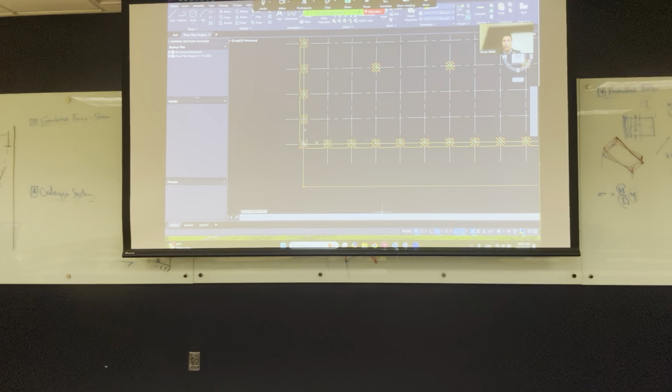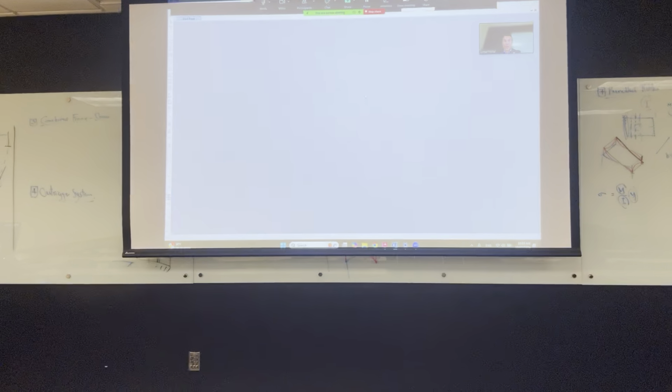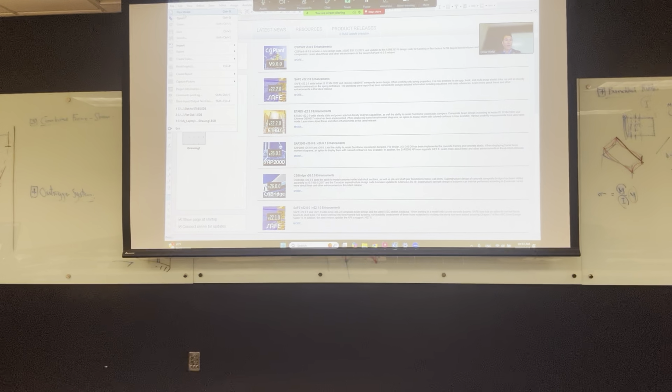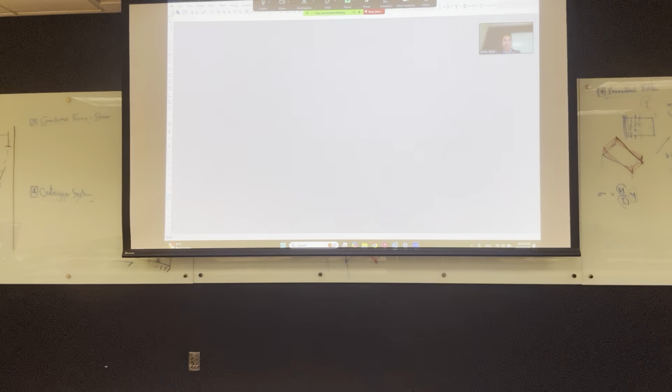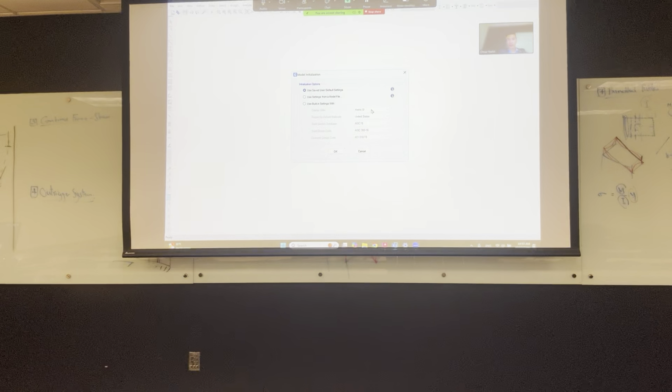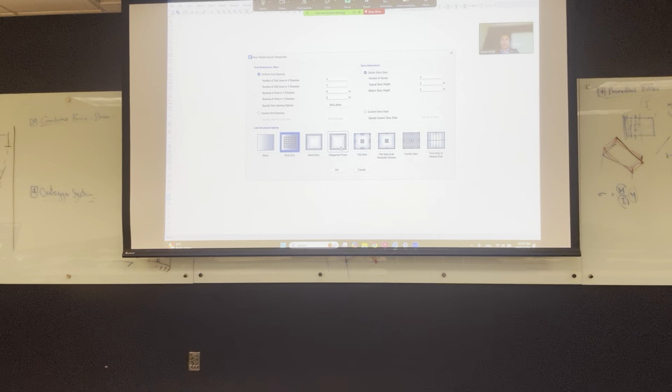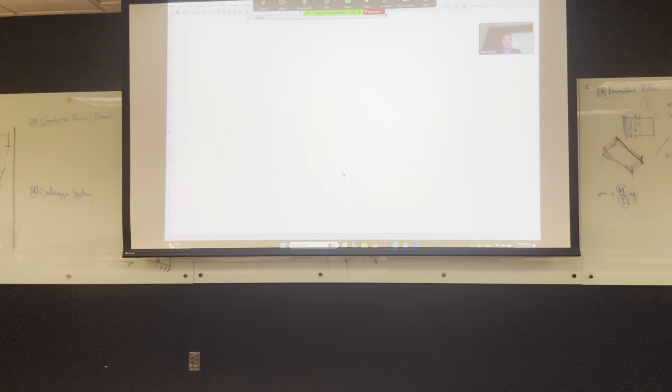And I will go to ETABS. And if you guys remember, we're gonna do File, New Model, and then I'm gonna pick the units. I'm gonna make it metric. I'm gonna say okay. I'm gonna pick blank, no grids, because I already have the drawings.